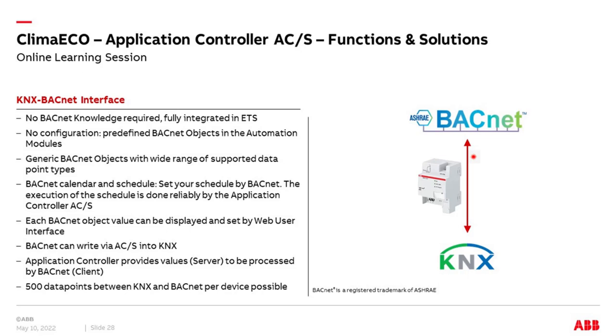The same happens with the solution here. Our BACnet server cannot do anything in the BACnet system itself. So we are not a BACnet client. This has to be done by the BACnet system itself. So how many data points can be linked? Up to 500 with one application controller.